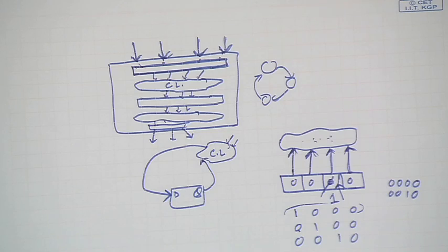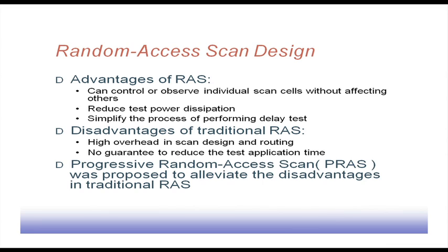The designer has put the flip flops from the design angle and they have put them as close as possible to the required portion. Now, later on when the test engineer comes, they have to design this scan chain. They try to make as good a job as possible, but that may not be sufficient. For random access scan, putting them onto this two dimensional organization may be difficult.